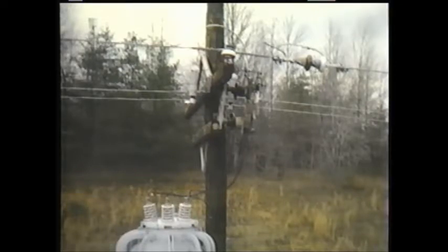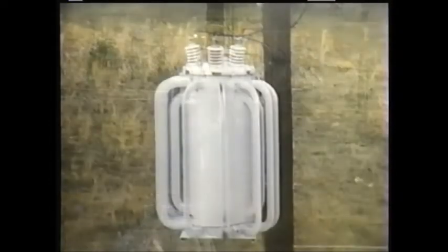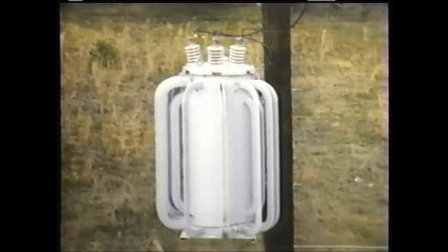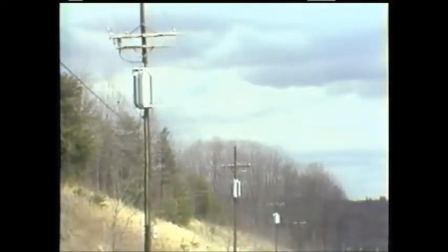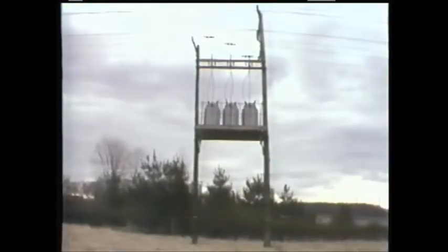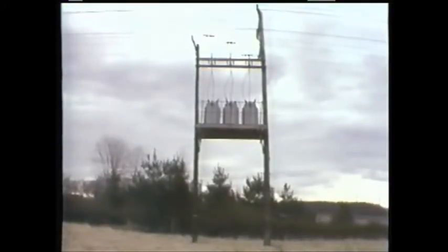Regulated voltage is supplied to the distribution system through a wire connected to the load side of the regulator. The wire also runs through the isolation switch to a tap on this side of the insulator. In most cases, each phase wire of a distribution line is attached to a separate voltage regulator. The regulators may be mounted on separate utility poles like these, or in some cases, 3 regulators may be mounted together on a platform.